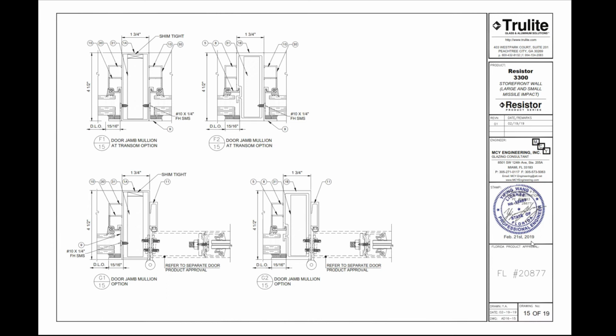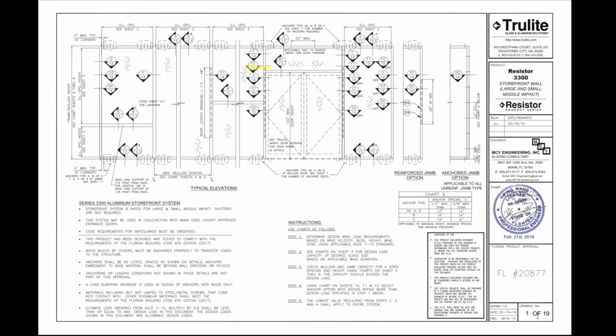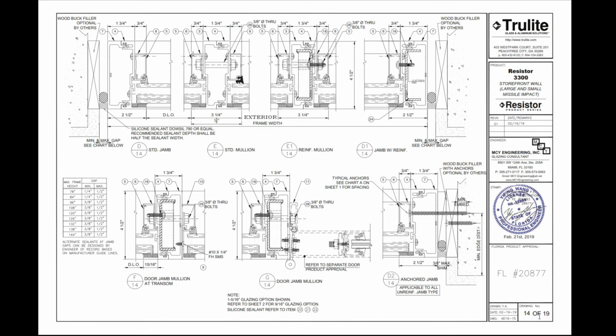And you'll notice that in this drawing, there's no door here. That's because you look at the location of the black line extending from that detail marker F2 on 15. It's above where the door is. Okay, it's above the door. Now G14, it looks like that line extends into the door. Sure enough, there's a door.